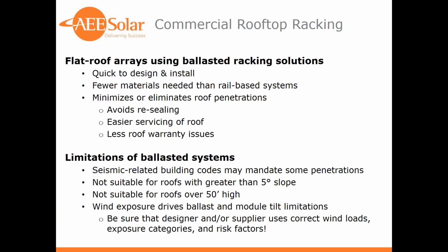So your wind exposure will drive your ballasting calculations, and be sure that the designer and supplier uses the correct wind loads, exposure categories, and risk factors. We do see some online tools for other ballasted systems that don't get a engineering review. All of our designs are reviewed by Aero Compact prior to being recommended to you as the customer.